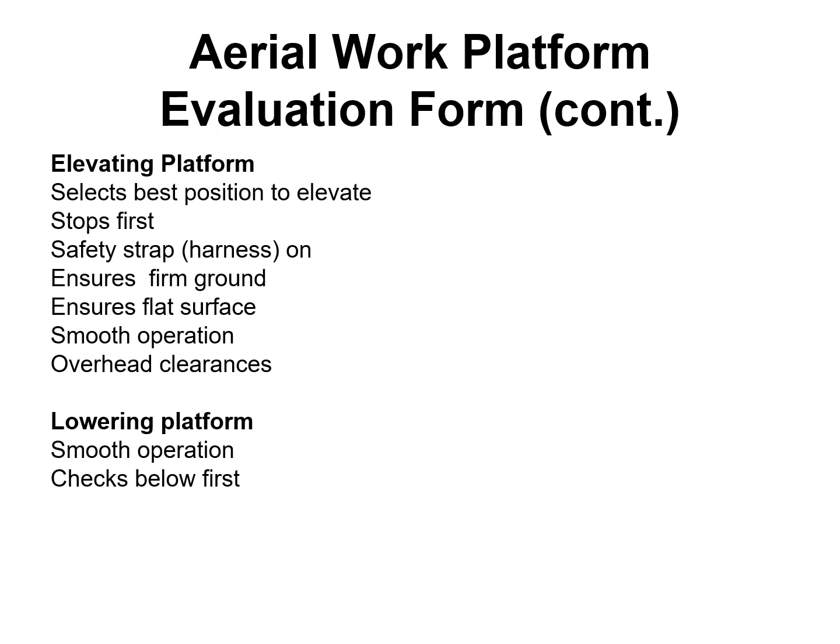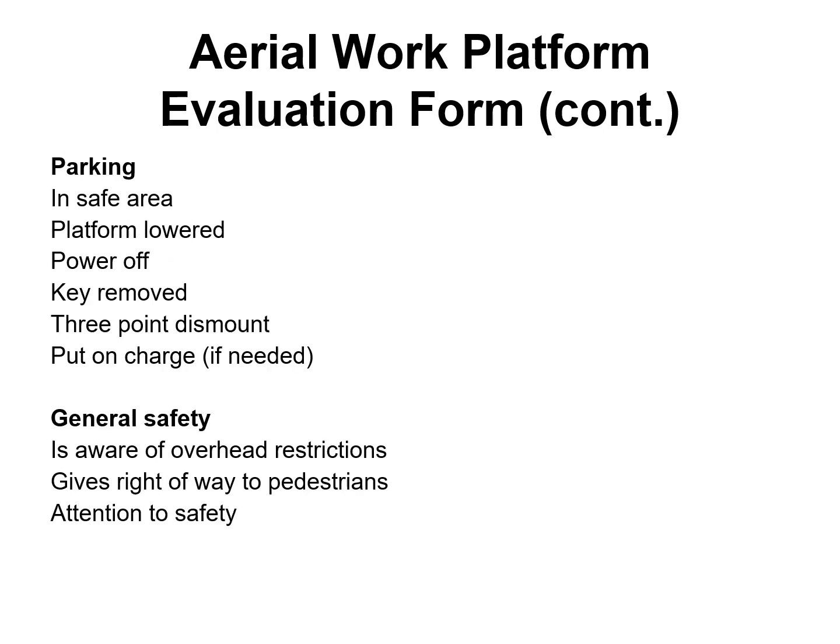Again, operating, we want to select best position to elevate. We want to stop first. If there's safety strap or harness, we want to make sure that we put it on. We want to ensure we're on firm ground, flat surface, smooth operations. We want to look for overhead clearances or hazards. When we're lowering the platform, we want to make sure it's smooth and check below first.